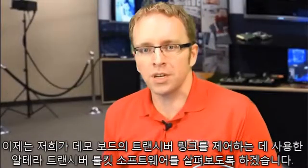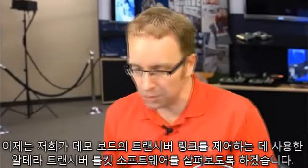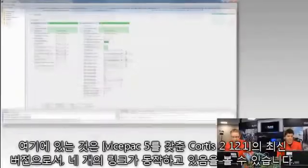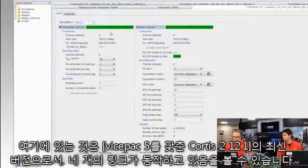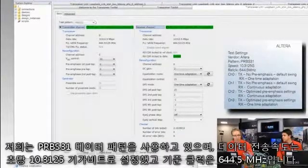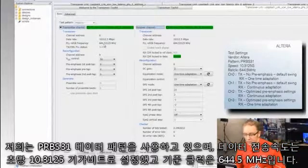Now let's have a look at the Altera Transceiver Toolkit software that we use to control the transceiver links on the demo board. Here we have the latest version of Quartus II 12.1 with device pack 5. And what you can see is that we have 4 links up and running. We're using a PRBS 31 data pattern, and we have the data rate set to 10.3125 gigabits per second and a 644.5 megahertz reference clock.